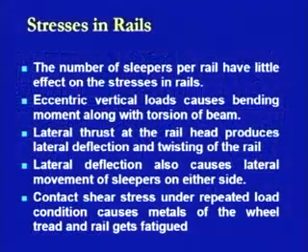Then the next thing is the contact shear stress. Now, this contact shear stress, as we have seen in one of the slides previously, where there has been an interaction shown in terms of cylindrical movements of the wheel on the cylindrical case of a rail. Now, when this type of contact is there, it may cause a certain amount of shear stresses because of the repeated load conditions.